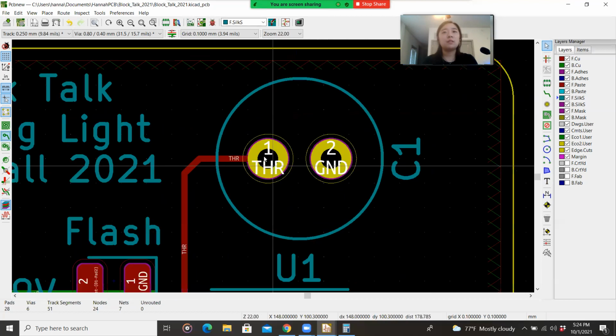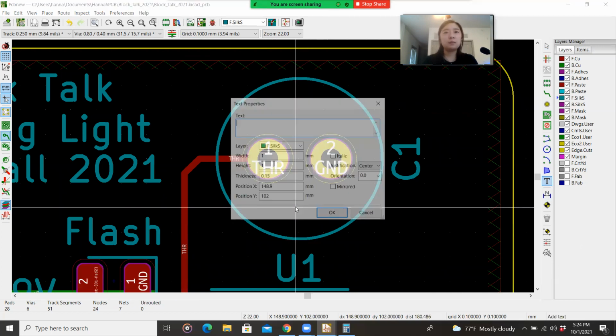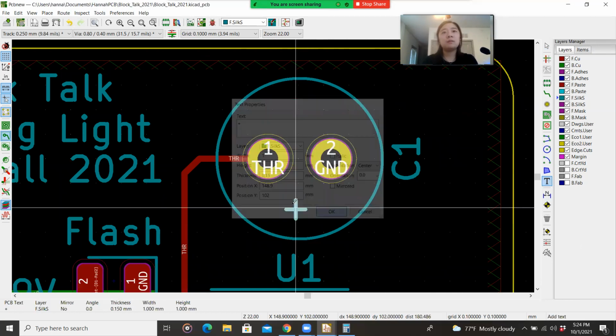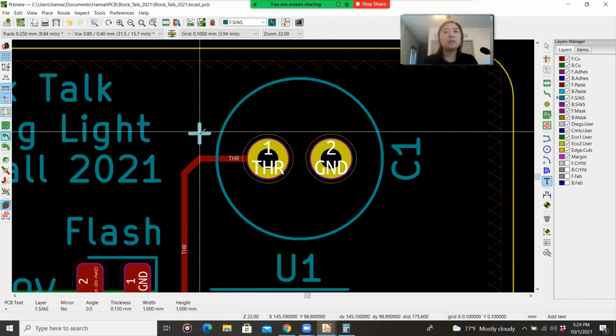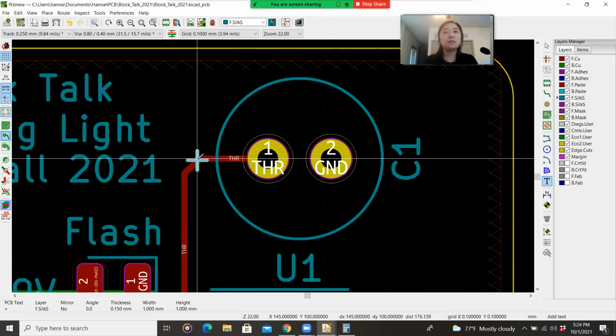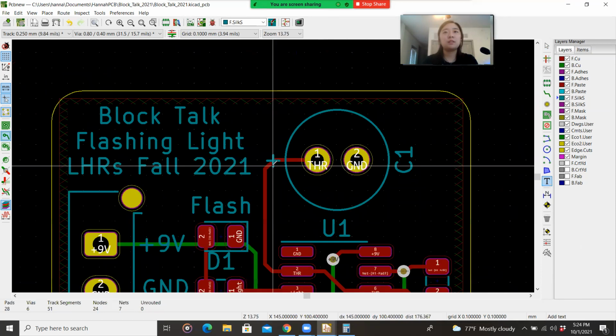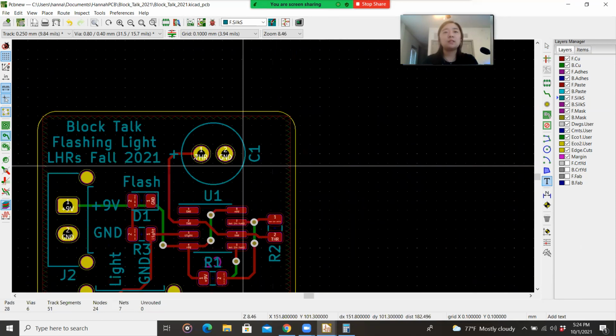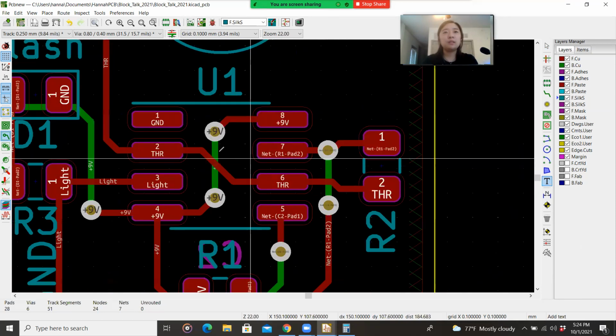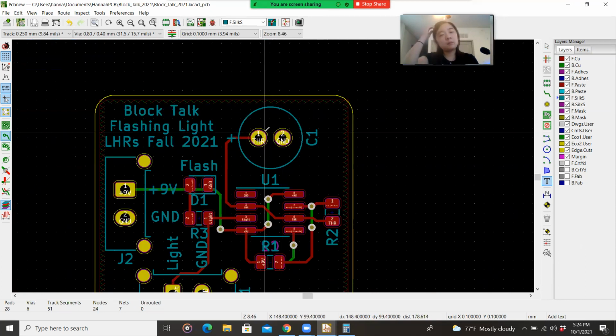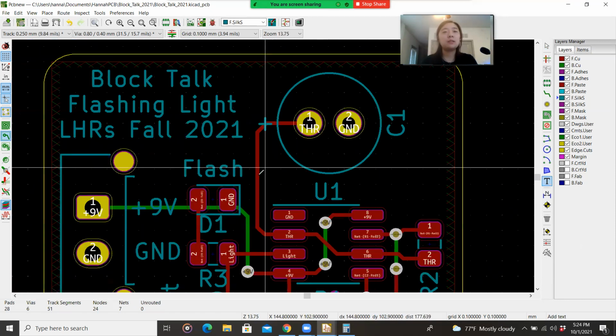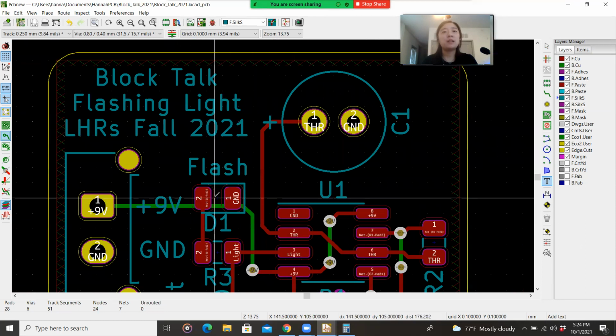And then a lot of times this is labeled, but here, just in case, we want to specify which side is the positive end. Like I said, you could put text on the copper traces and that's okay. With polarized capacitors or anything that's polarized, you do want to specify in some way what's positive and negative.